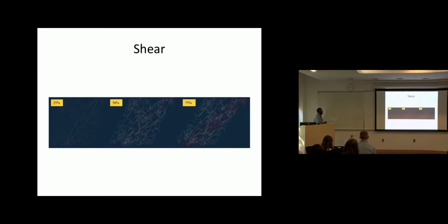And to see why that's the case, I have plotted, here you can see these plots. As you're increasing the shear strain, these fibers are getting aligned. And when you shear it further, the only way you can cause further deformation is by stretching the fibers. So at low levels of deformation, fibers can bend. At high levels of deformation, the fibers have to stretch. And bending is easier than stretching. It is for that reason that this material strain stiffens, okay? And you can see that also in tension.